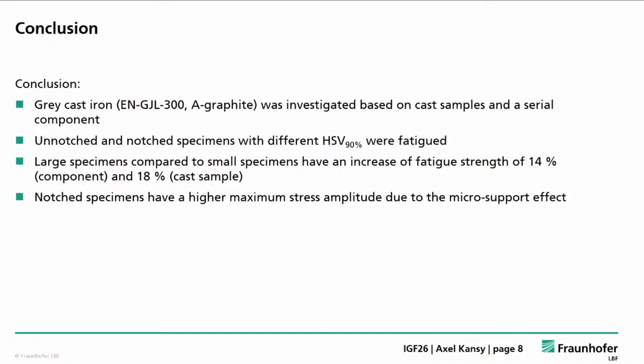The material has a network of graphite lamellas, and there can always be the start of the fracture because the lamellas serve as an inner notch.